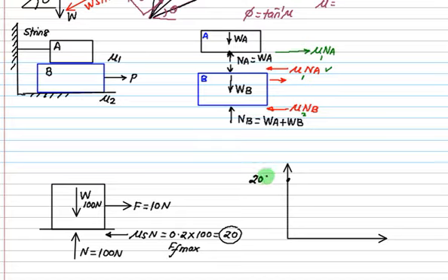Now if you visualize the figure, what is the maximum value of friction force? Is it 20 Newton on this graph, at this point? But how much force am I applying? Only 10 Newton. Is this 10 Newton sufficient to overcome the friction force, or not? So are you in the region A to C, something like this? You are inside here. Is this a static condition? And if it is a static condition, is the value of mu less than mu s?